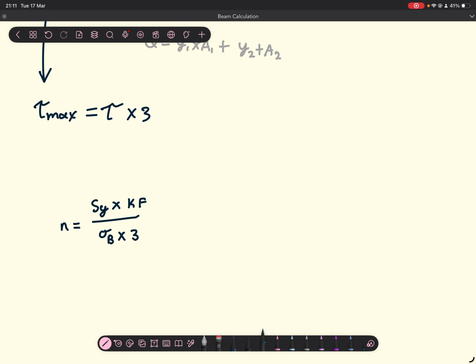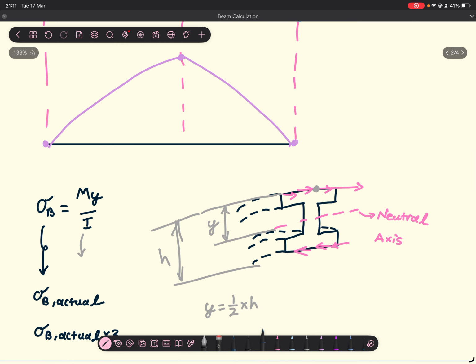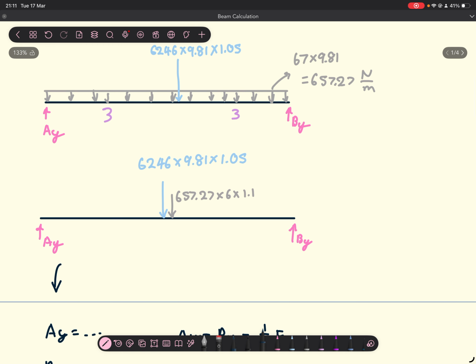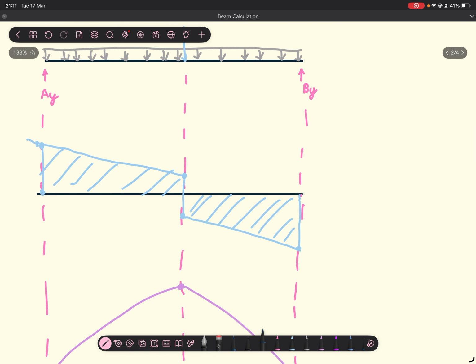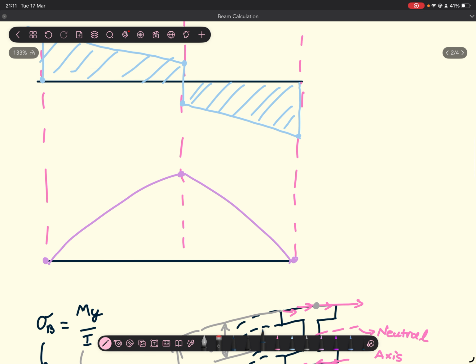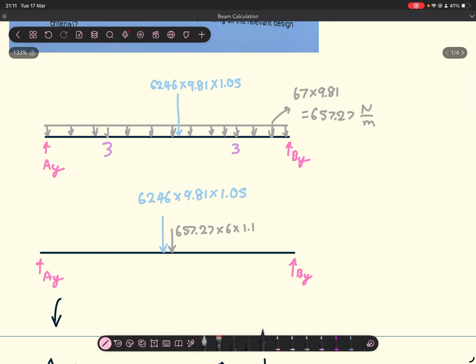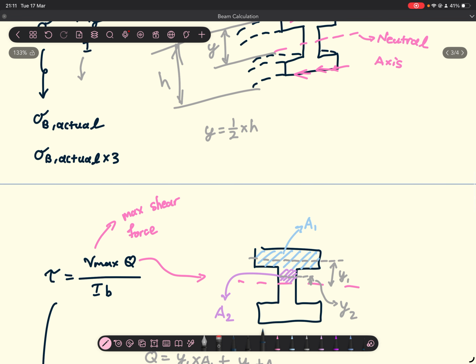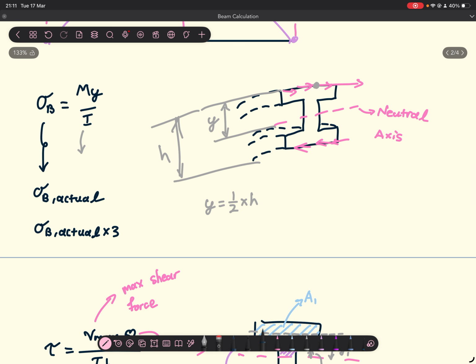That's what we're looking for, because it's very well and good to put a safety factor of 3 and put all these load factors, but you'll find that your material is actually not capable of handling all those loads, because all the calculations we did before are load calculations. So from this point all the way down, those were all load calculations, but we never really went back to our material and saw whether or not our material is actually capable of handling those extreme load cases.